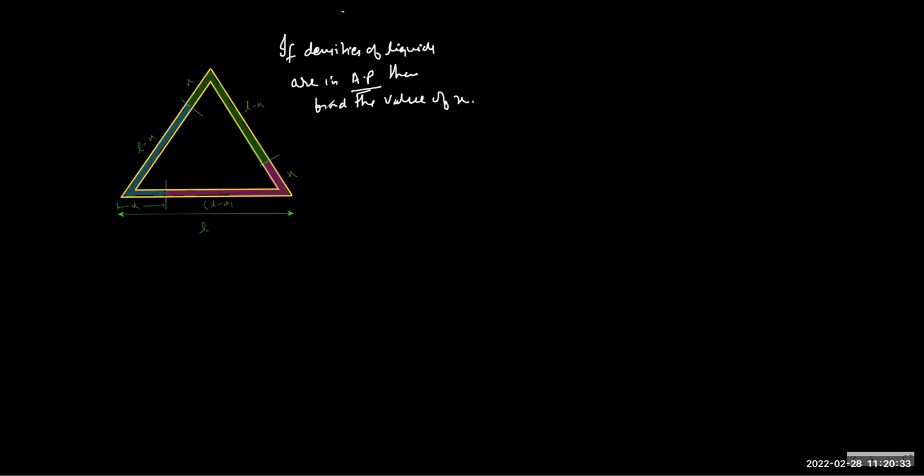So the way to write is simple. Write the pressure here, write the pressure here, because the horizontal part will have no difference of pressure because it's the same level. So how to write it? Let's say the densest is rho 1, the lightest is rho 3. So we can write rho 3 and x. The sine 60 will cancel out from both sides, so I'm not writing it. And you can also write rho 2 into, and on the right side it is this.